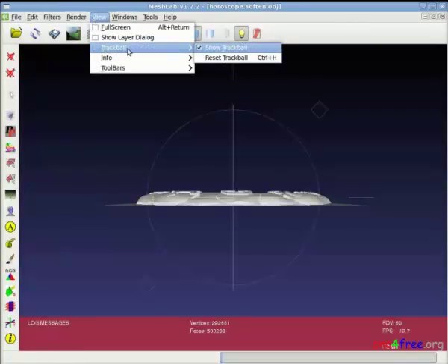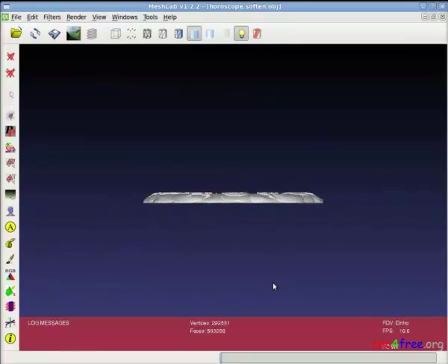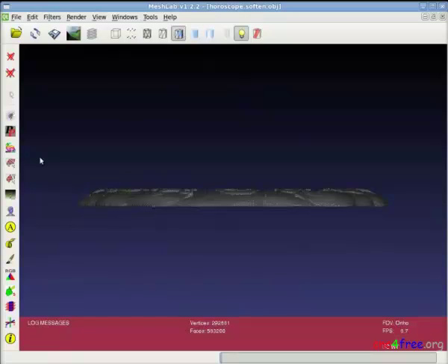The View menu hides the on-screen trackball, providing an unobstructed view. MeshLab uses a perspective view by default. With a cursor in the view, pressing Shift and rotating the mouse wheel establishes an orthographic view. View magnification is adjusted using the mouse wheel. Flat lines display mode ensures all faces are visible.